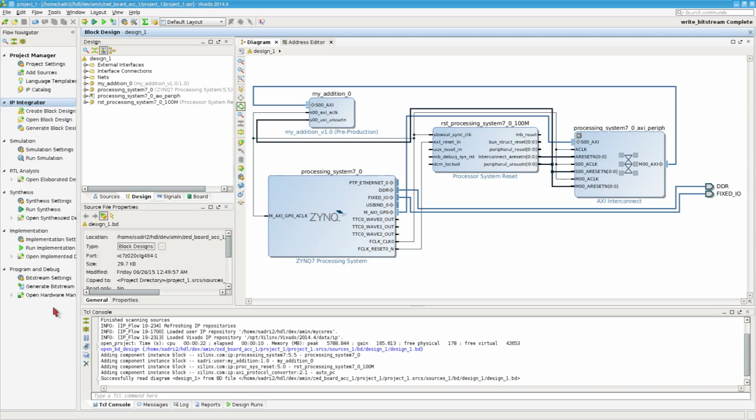For each of the 4 hardware accelerators I do the same. I create the project contains the ZYNQ PS and the hardware accelerator, and then I create the Bitstream. And these Bitstreams are practically those Bitstreams that we store on the SD card. And then whenever we need one of these specific acceleration tasks, we program the PL with that Bitstream.